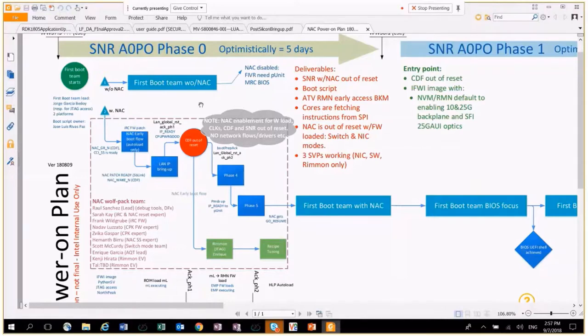So on day one, it gets put into the board. And once it's put in, there is a notion of keeping all the individual blocks in reset mode, right? So this is done either through some JTAG interface or some register write or any of those, right? So by that, you mean you are not letting anything run.